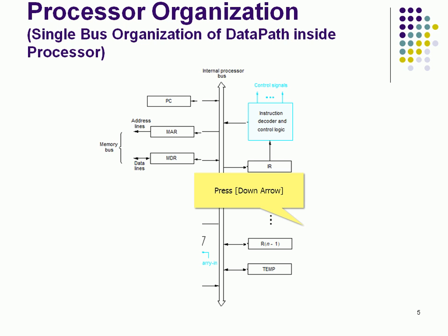So the instruction decoder will be there. After decoding the instruction, it will understand what kind of control signals need to be generated, whether add operations, load operations, store operations, multiply operations, and so on. There is also a memory read operation. This kind of semantics will be brought out after decoding, with the help of the control logic. So these are some necessary registers which will be there in a CPU.